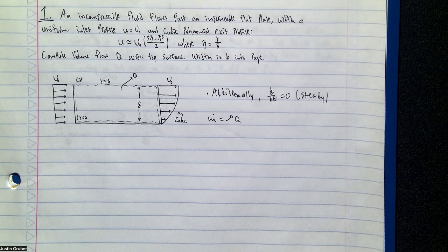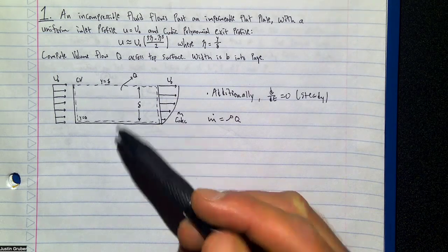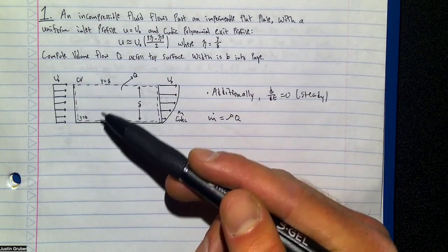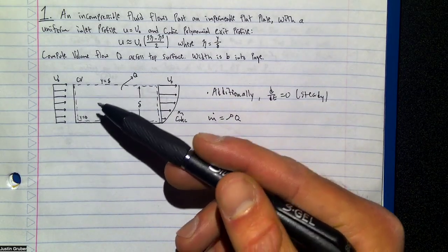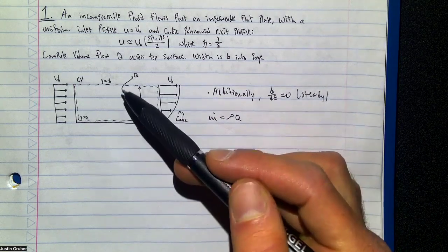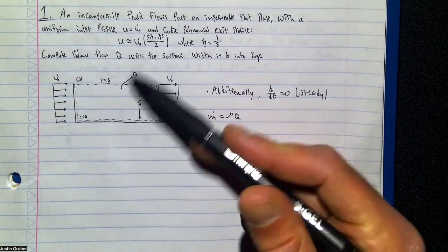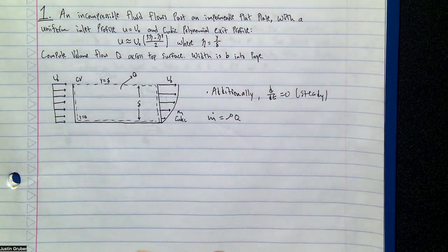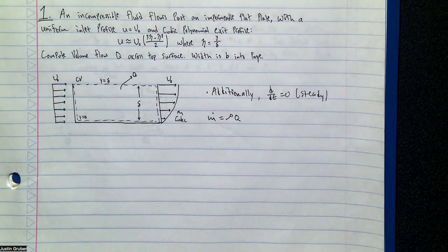This is where control volume analysis gets really powerful, because we don't care about the dimensions of this top end. We just know, by virtue of conservation of mass, that we're going to have some quantity flowing out. We're not going to use any sort of dimension stuff to compute that. We're just going to subtract stuff out. So let's get into it.